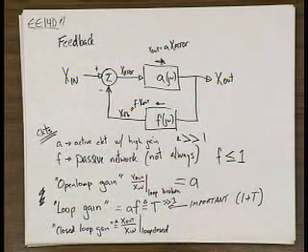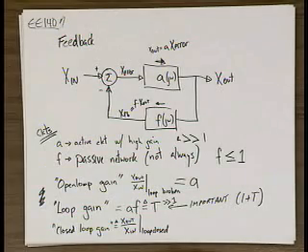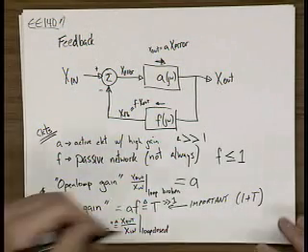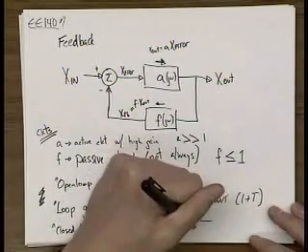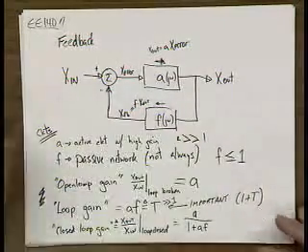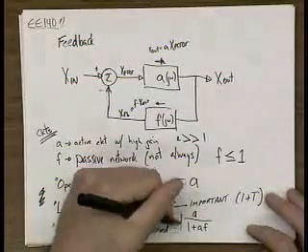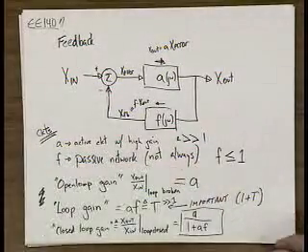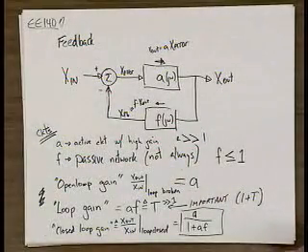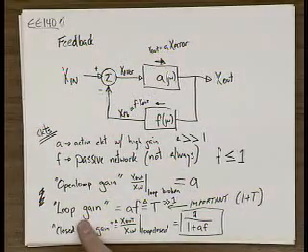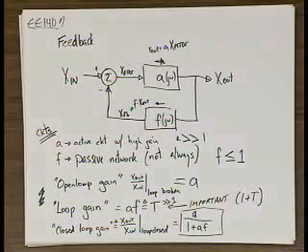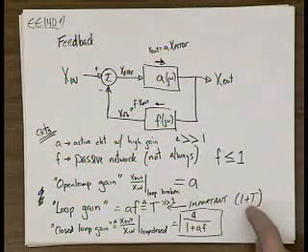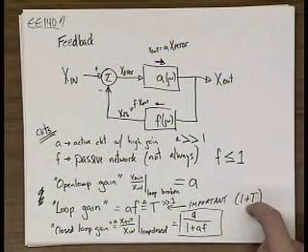And I suggested all of you do the math yourself to verify the answer that I'm about to write down, because again, this is important. It's equal to A over 1 plus AF. Okay? It's another very important result. The closed loop gain is the open loop gain divided by 1 plus the loop gain. That term 1 plus T just showed up. Okay?